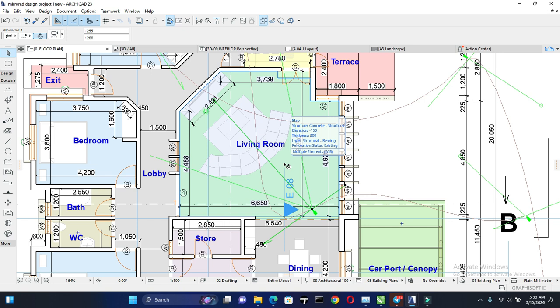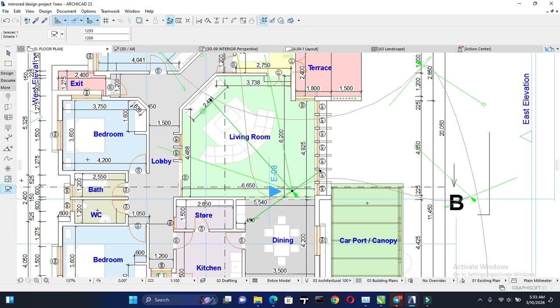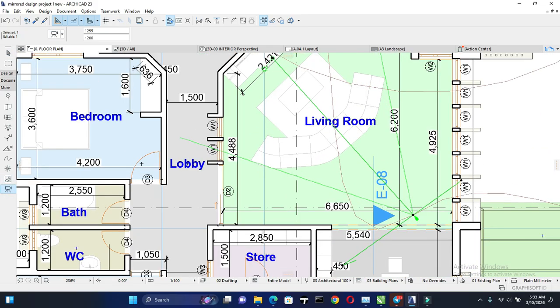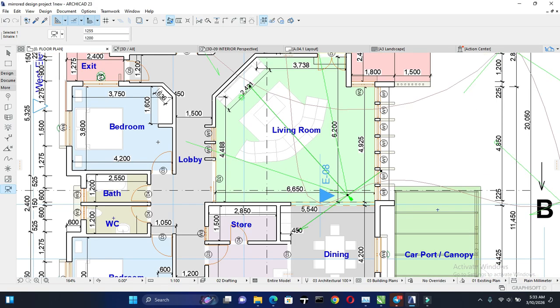So I will find the camera in my views. So I select the camera, check the name of the camera, it's my scene, and it's camera 7. So the initial position of the camera is 900, and the target is 2100, and it's looking down to 900. I don't know, do you understand? But then let's make it 1800.